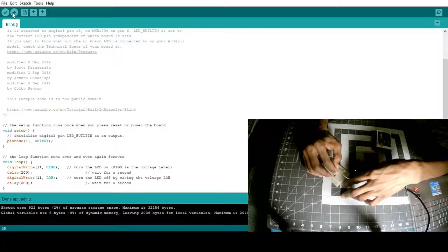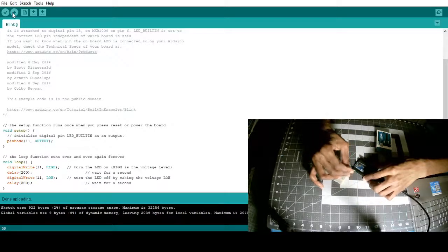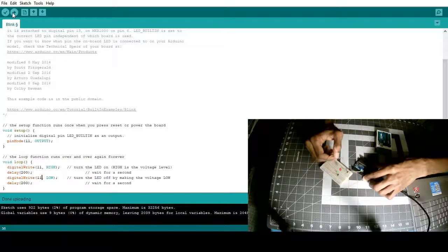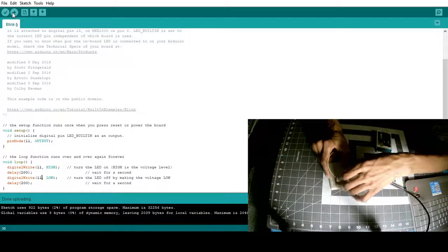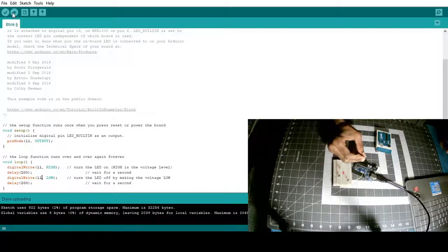So I put pin number 11 on the bigger side. Then you have the resistor here. We have a resistor of 220, it will work well. And in series, the other side, the minus of the diode, I put it on GND. It should go like this, GND.